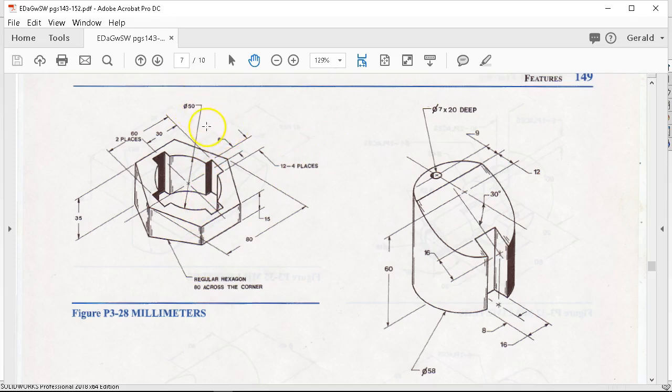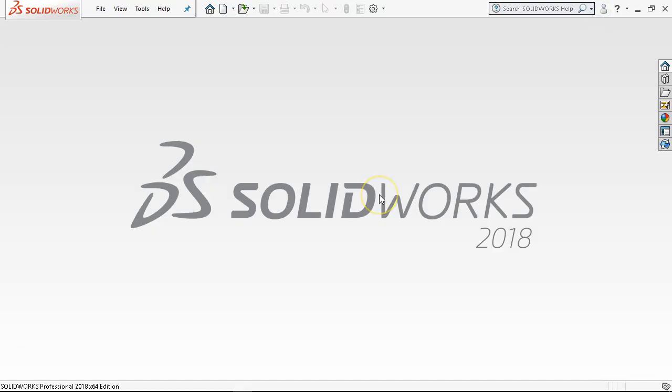the 50 millimeters, I had a couple of students say, well, if that's lying on that face, how do I get it to go straight through? Well, first of all, that's definitely not a best manufacturing practice because the bottom is going to be elliptical. And then that shape becomes really weird. We'll do it that way so you have the explanation, but we just probably quadrupled the cost of that nut because that resulting geometry is going to have some issues. So we'll try it. It'll be an experiment. Not that I haven't painted myself into enough corners.